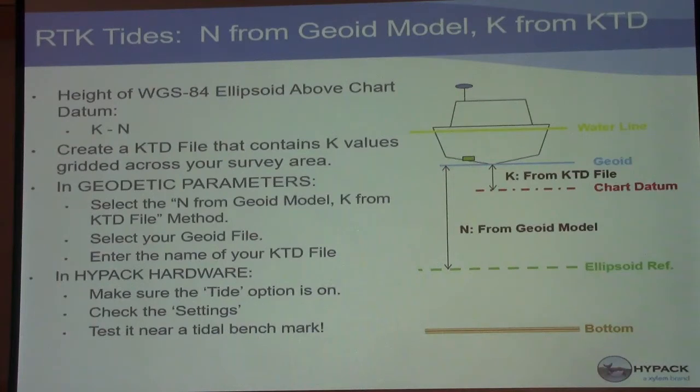Well, if I just take and run an RTK and go over to these gauge boards or these monuments that are already set up along the river, they don't check in with the elevation, even though I'm pulling RTK values. There would be quite a significant amount, to the point where I'm scared to use RTK ties, for fear that if that's what's coming into HYPACK, I'll be that distance off versus just using a gauge. Are you using a heave sensor and everything too? No, so it's just a flat regular. Most of the time when I make my check, I'm checking against a static location. I can pull right alongside and set it down, either a chisel mark or something like that.